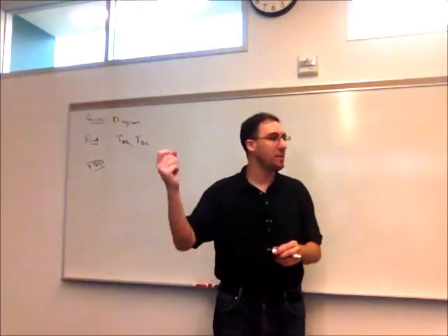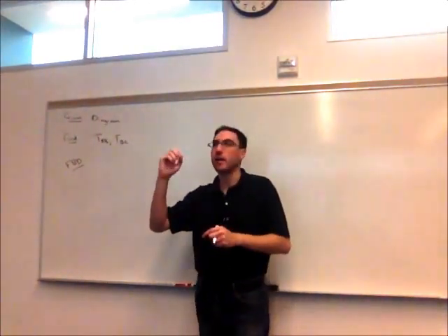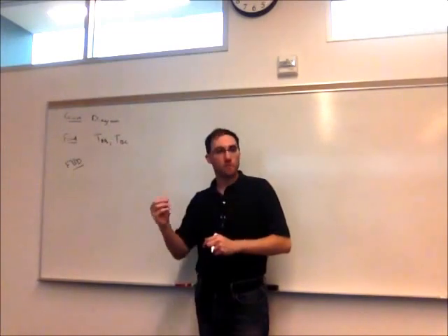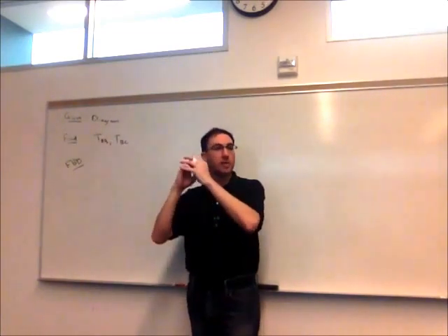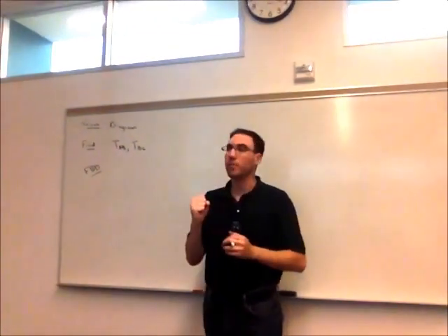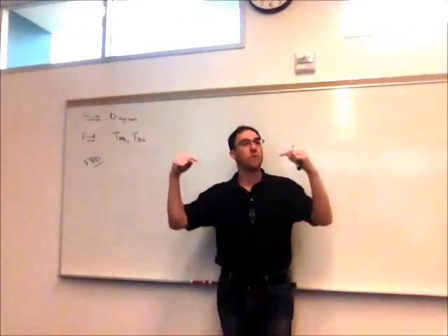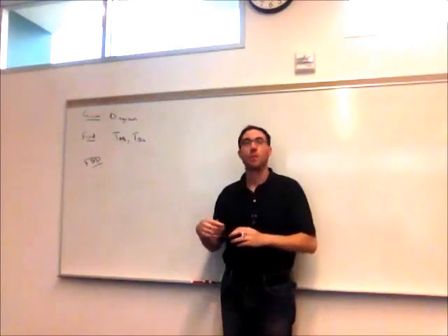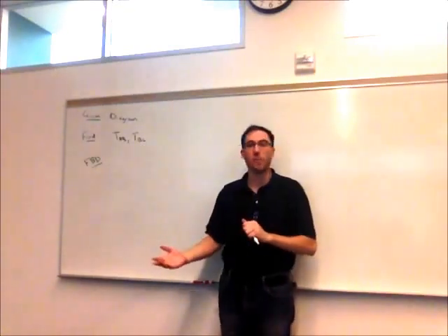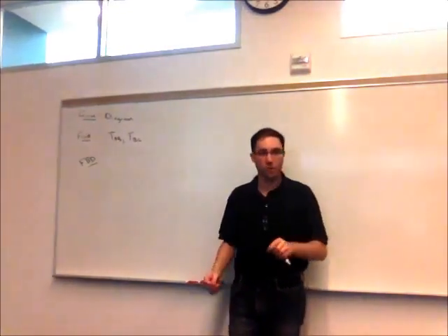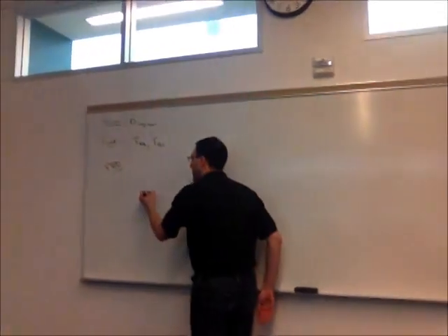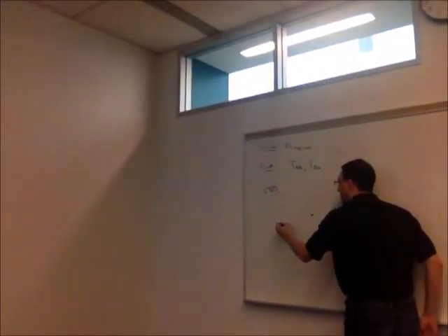Right, so that ring at B. So that ring is a 3D object. For this chapter, we're simplifying it down to a single particle. For particle equilibrium, what that means is all forces act concurrently, which means all forces act through that point. When we get to chapter 4 and 5 and beyond, when we have rigid bodies, that's no longer true. So to simplify this, we represent that ring as just one dot.